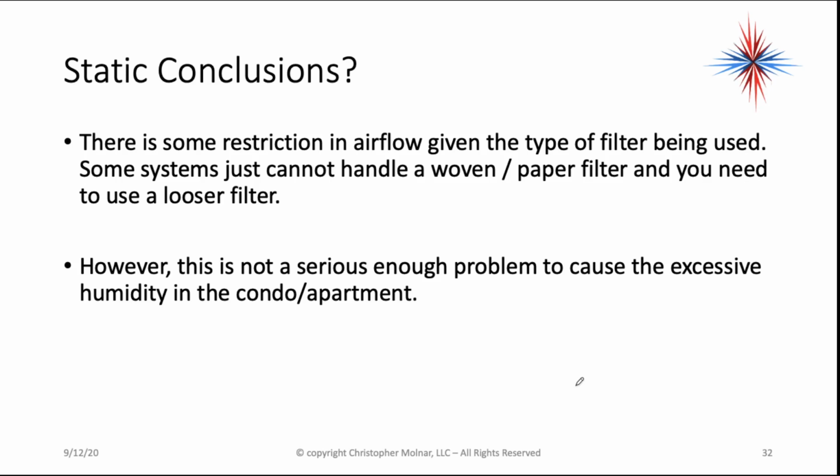Conclusions based on static pressures. There's some restriction in the airflow given the type of filter being used. Some systems just cannot handle the woven or paper filters. You may need to use a looser filter. However, this is not a serious enough problem in this case to cause the excessive humidity in the condo or